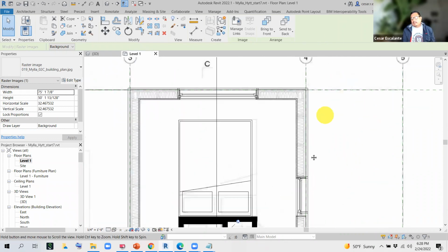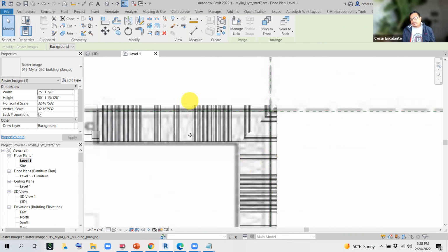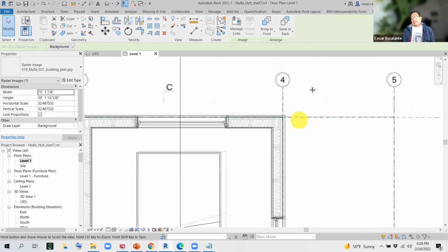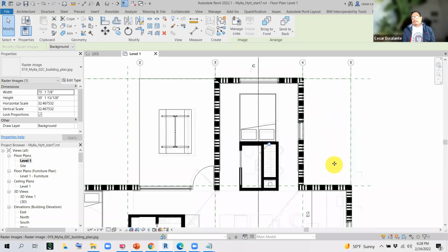And if you look at it, it will expand across all the interior finishes, all the interior layers. And because in the fill pattern definition, I say to align with the object, if there are changes in the rotation of a wall the pattern remains aligned.